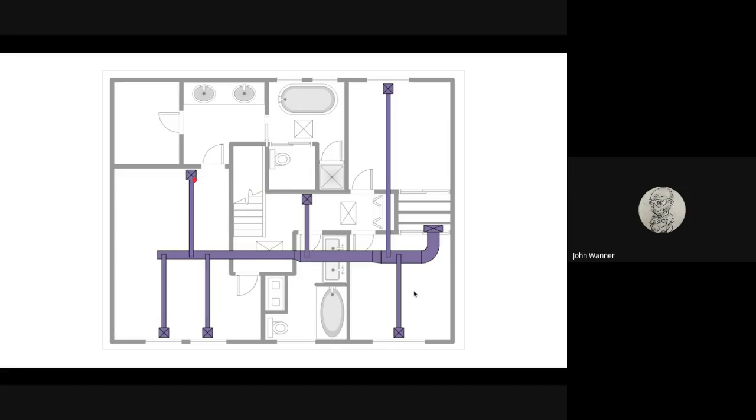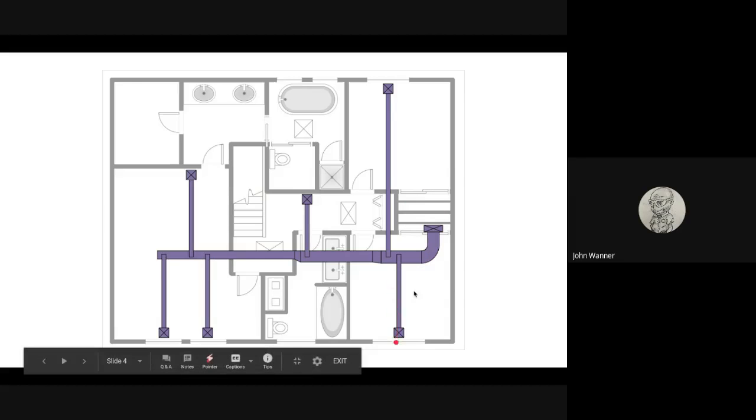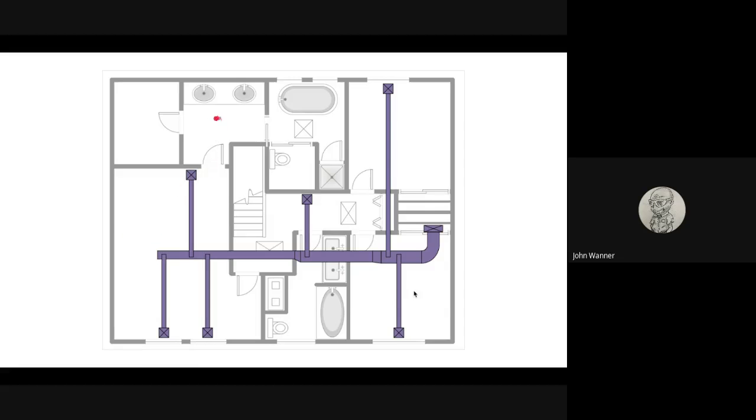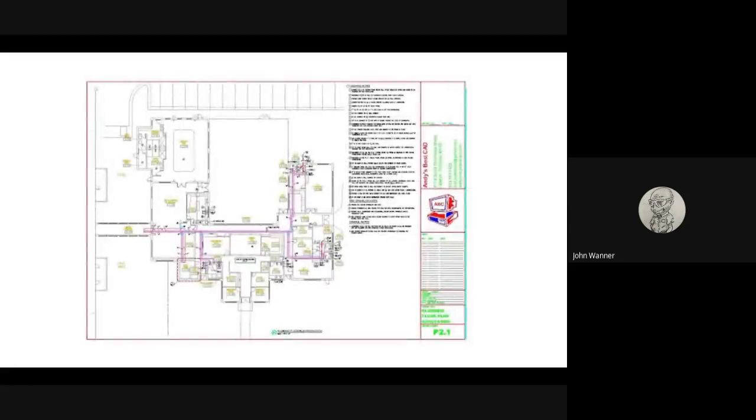That's a symbol for an air register. And if you look up in the ceiling of your house, against the ceiling, you'll see a spot where the air comes out, and that's the symbol for the register there. And you can see this is the main trunk line. And this end here is blowing down into an engineering section as it comes up. This is all space for running pipes and wires. And then it runs to each room. And you notice it's located near the windows, plus one here, the door, because there's not one in the bathroom and closet. That's heating, ventilation, and air conditioning.